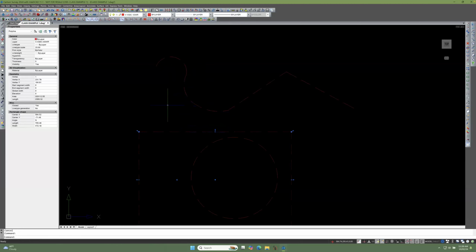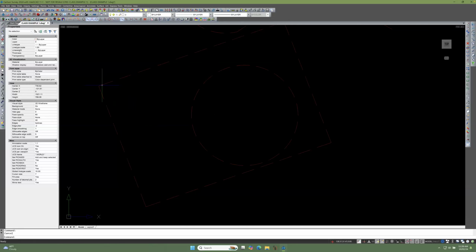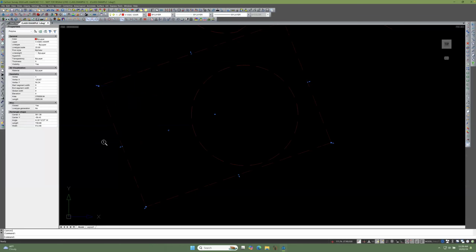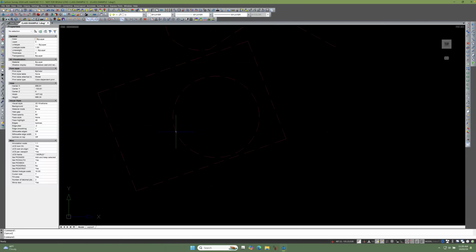Now this was done with the draw rectangle command. So you can do things like rotate the whole container. You can grab the corner, the little arrow, and it stays rectangular. But if you grab the rectangular grip, it just does a vertex edit, whereas the arrow keeps the rectangularity of it. So there's just different things.